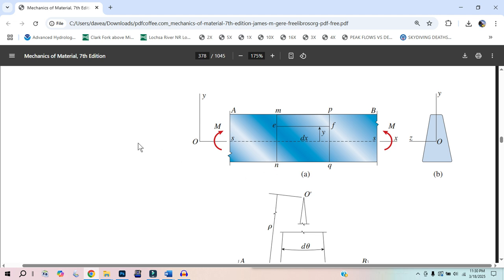So if I have a 1 inch bar of steel and I stretch it with 50,000 pounds, that's its limit. But if I have a half-inch bar of steel, I can only put half the load, 25,000 pounds, let's say, and that's its limit. And so we use parameters of percent change in length. You know what I mean? So that's stress, and the change in length is strain.